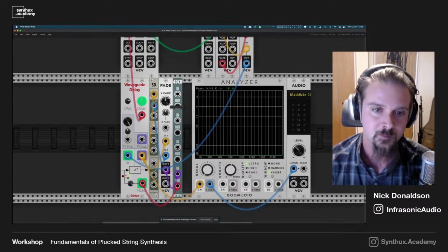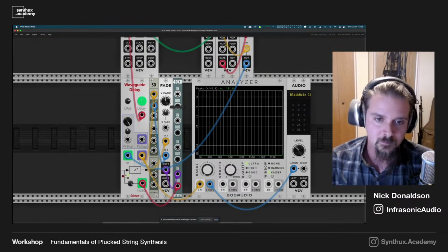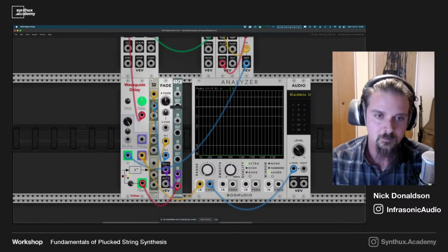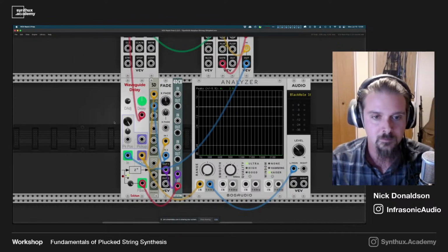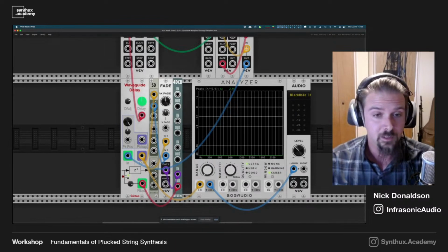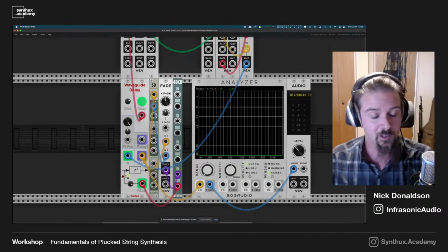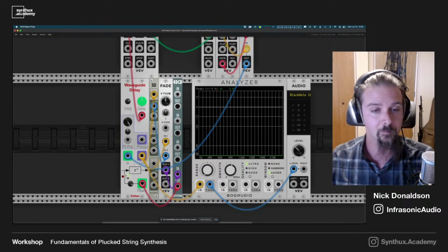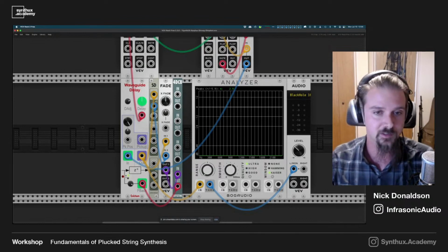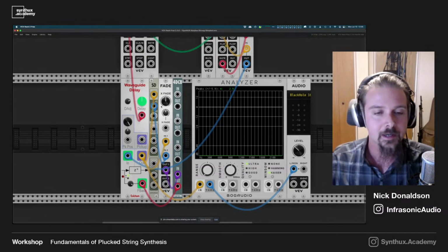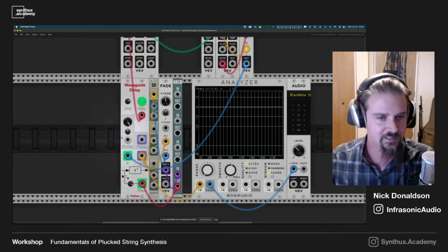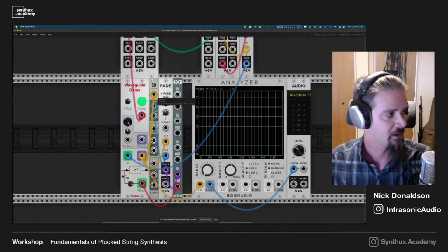And can you actually make the effect more pronounced if you would work not with one sample but two samples or three samples? Sure, absolutely. If we made this longer, there are so many different filters you could use here, and we could use a longer running average filter that would change the low pass response. This just happens to be the simplest thing. This is what the original algorithm was using, this two sample FIR filter. And I think I saw somebody in the chat ask to go through this again.